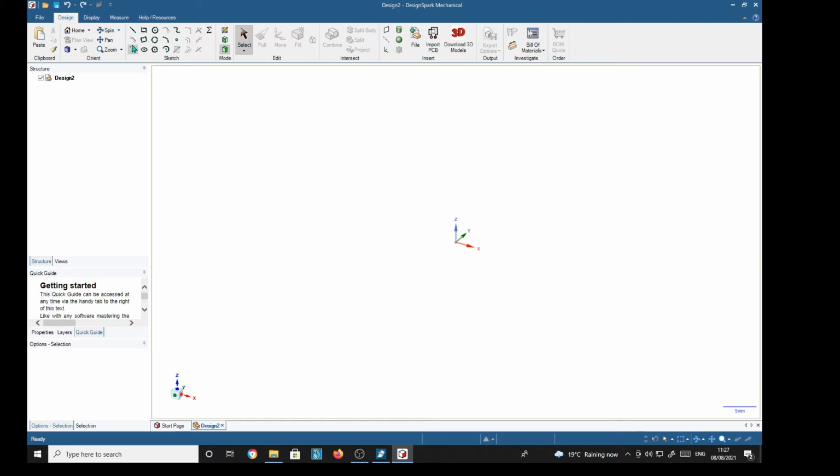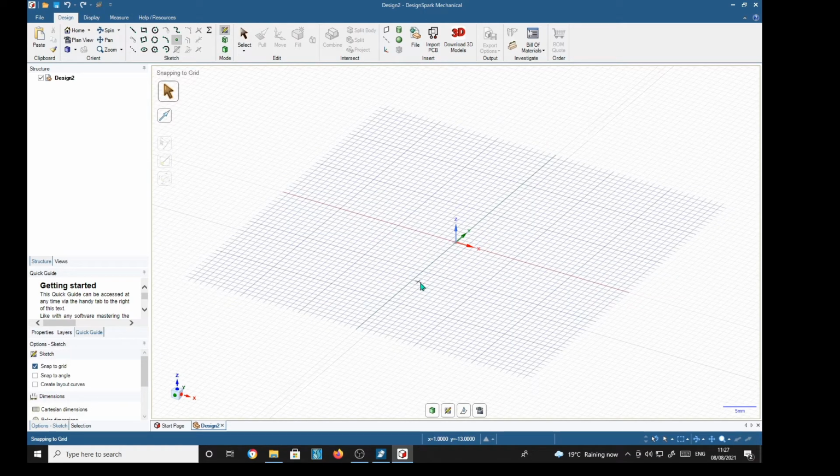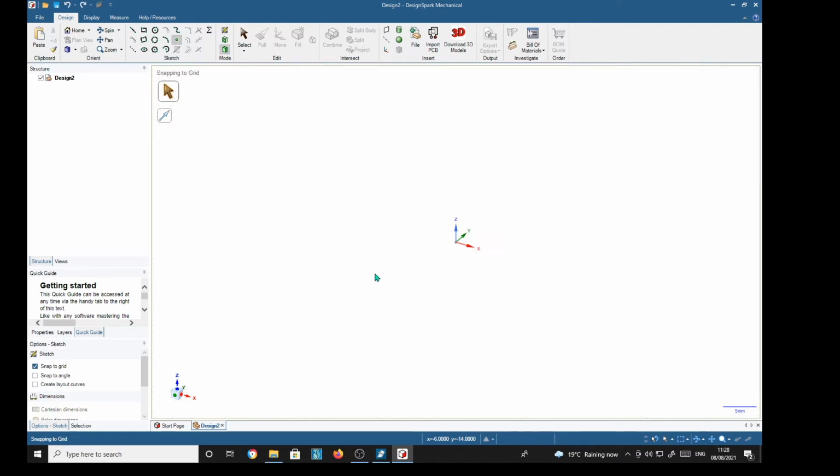Now suppose we want to say drop a point somewhere, and well, we'll get the sketch plane back. Try again with the D key. Right, we've now got the 3D environment, but there's no indication of what we're trying to draw. We've got the point over here selected, but if we try and click anywhere, nothing happens. Click, click, no. Well, the point is, you see, we're in a 2D plane here, and good old Design Spark Mechanical doesn't know at what depth we want the point placing.